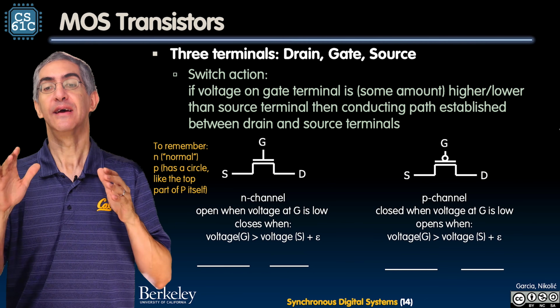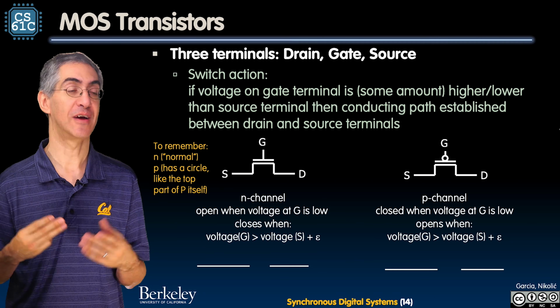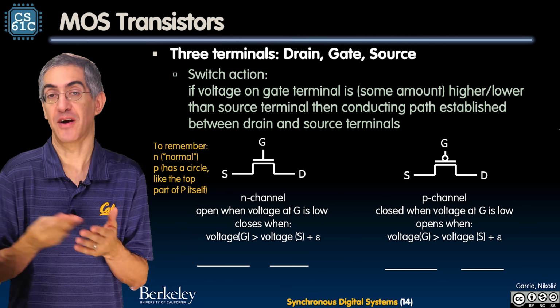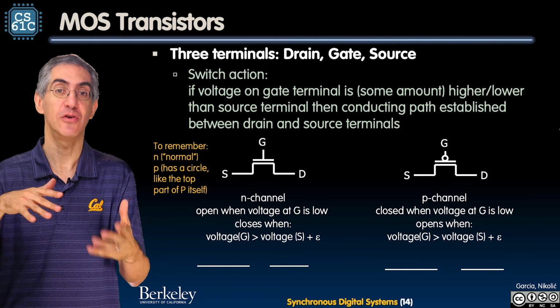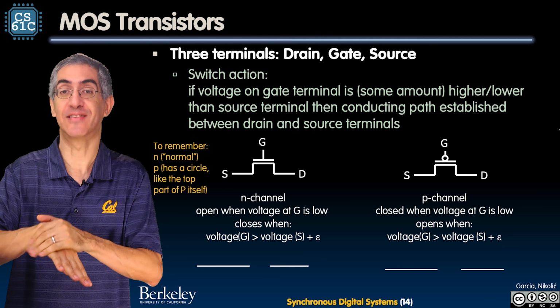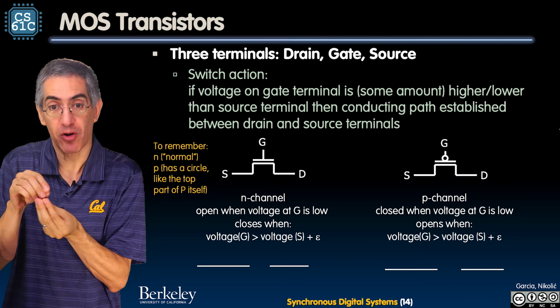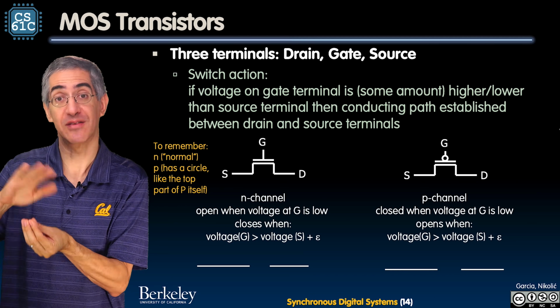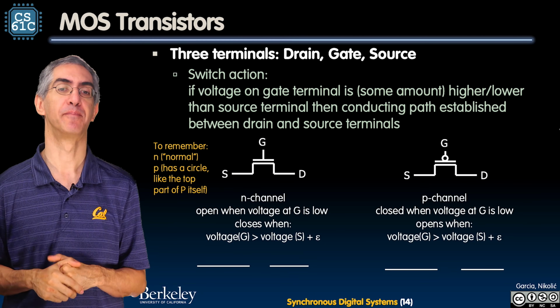So here's a picture. A transistor is usually a three-lead device, and you can tell whether it's going to be used as an amplifier or not by whether it has a heat sink on it, because these things get hot. If it's a big one that has a big heat sink on it, probably it's used as an amplifier, and that heat sink is being used to dissipate that heat. If it's a smaller one, if you go to the electronics store and buy a smaller one that doesn't have a heat sink, probably it's used as a switch device, or as a low-level amplifier.